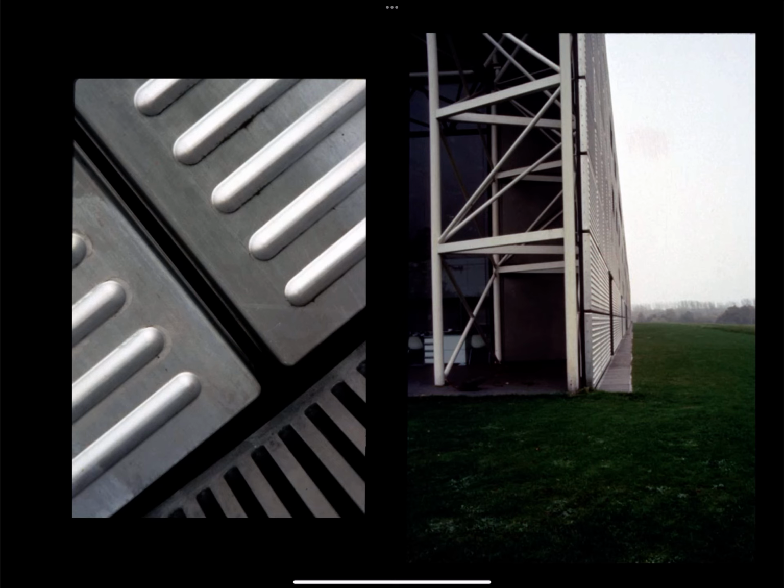The roof trusses are not flat, as I mentioned before. They are cambered across the 110-foot span of the building. So they are 6 inches higher at the middle than at the outer edge. And so the roof is very, very slightly sloped. And this, of course, helps to get the rainwater off this basically flat roof, this low slope roof.